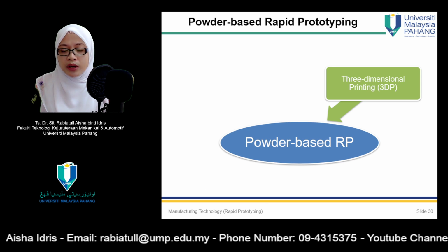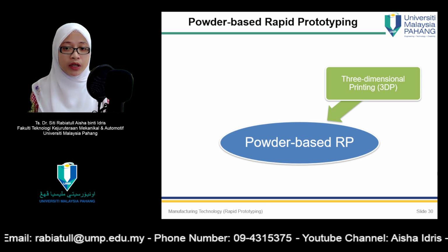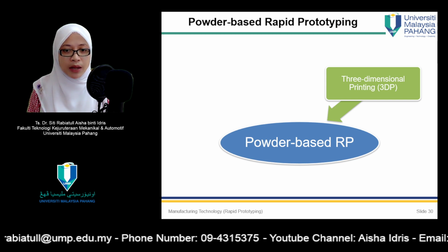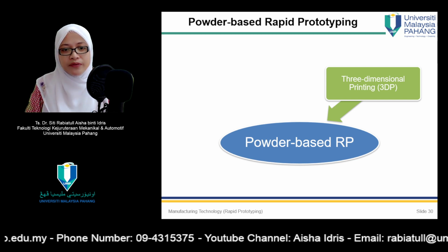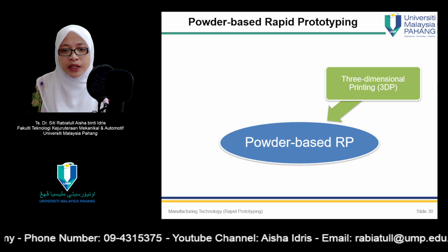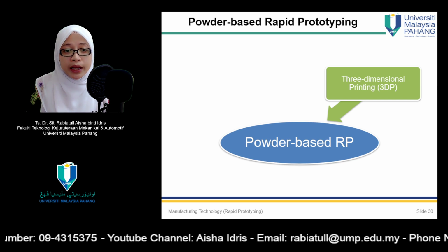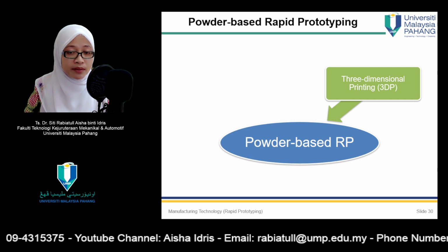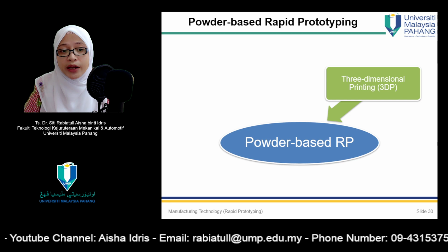Okay, now let's look at 3D printing. This RP technology was developed at MIT, the Massachusetts Institute of Technology. 3D printing builds the part in the usual layer by layer fashion using an inkjet printer to eject an adhesive bonding material onto successive layers of powder.